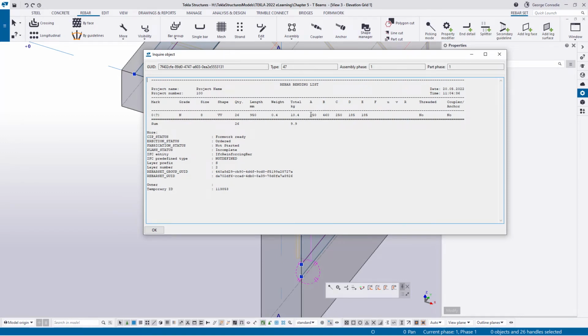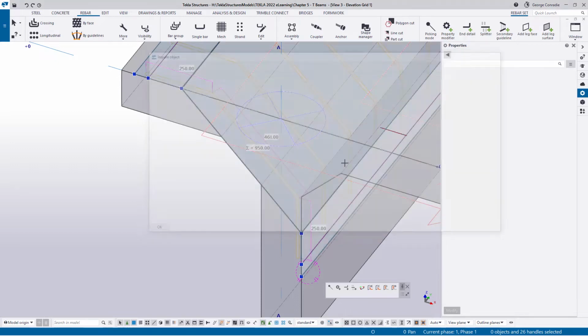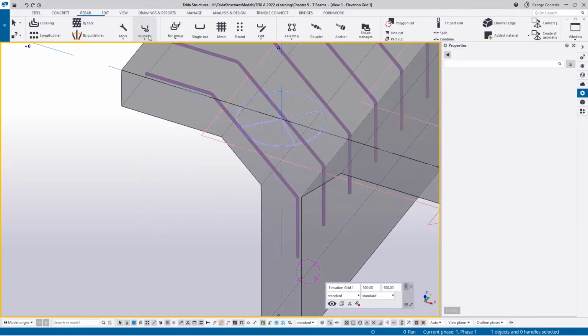we do have the first leg as 250, our last leg is 250, and then the skewed leg at 264, and then the 45-degree angle, which is measured in offsets, is then 185 by 185, which gives us the 45 degree to generate the 460 length. So with that, I think that leg is done.